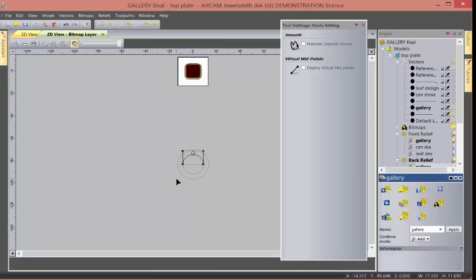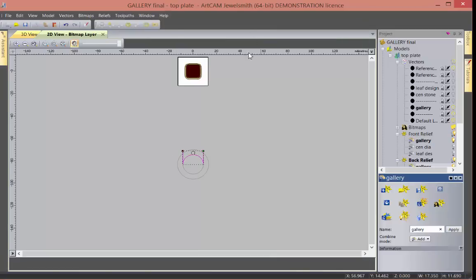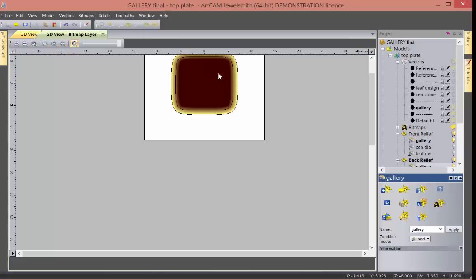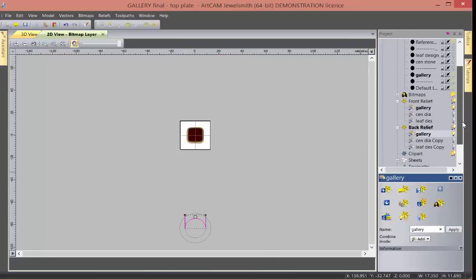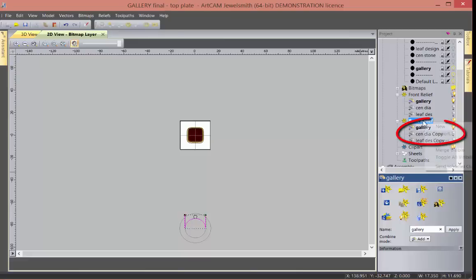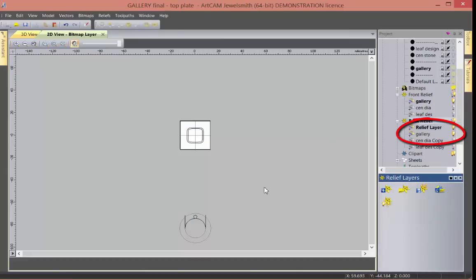Now we can cut our groove right through the bottom of our ring. Okay, so let's bring on our reference lines again. On the back, because we're working on the back, we're just going to make a new layer now. Okay, I'm going to do this sweep right here. So selecting this line, shift, grab our sweep. Okay, let's go to the Weave Wizard.